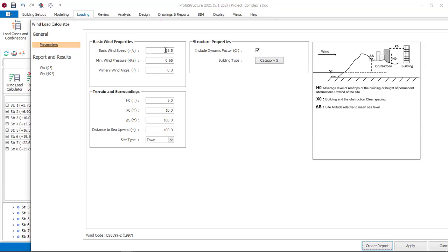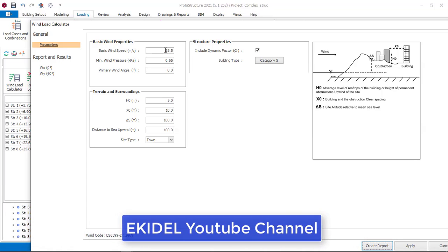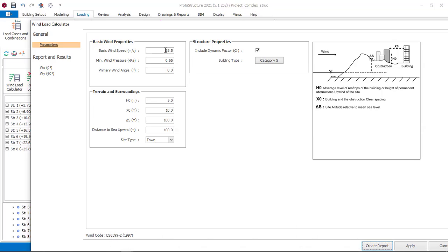Also, I was designing a building for a client in Jamaica, and I tried to research to find any weather scientist in Jamaica, but I couldn't find one. So I just went to Google and checked the highest wind speed that ever occurred in Jamaica. Google gave me 75 meters per second, and that was in the 1970s, when everywhere was plain. There were not many buildings, all they had were just trees and vegetation. So I used that wind speed.